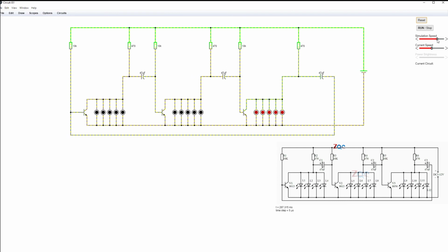We're going too fast. Okay. So here we see our lights are flashing. They're flashing kind of slowly. But then again, this is in milliseconds. So let's see if we can make our simulation slightly faster. We're going to go to other options. Let's give it a time step of 50 nanoseconds because we don't have to be as accurate as 5 nanoseconds.